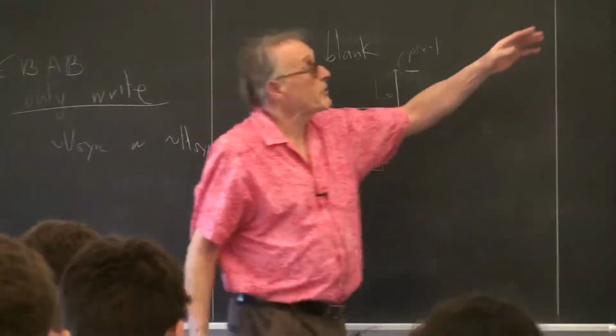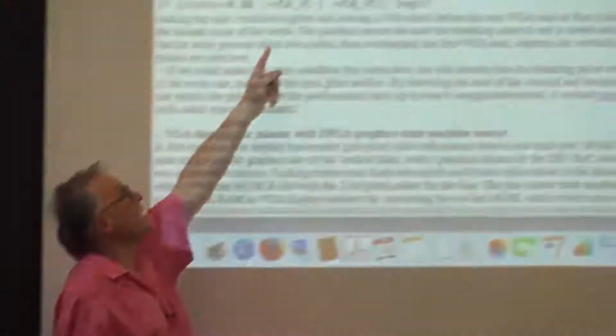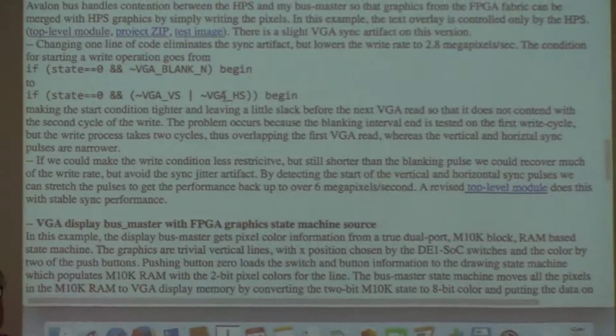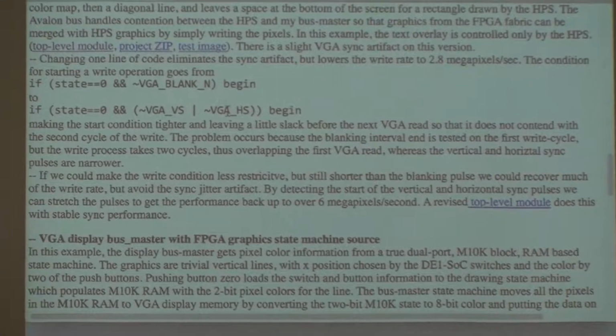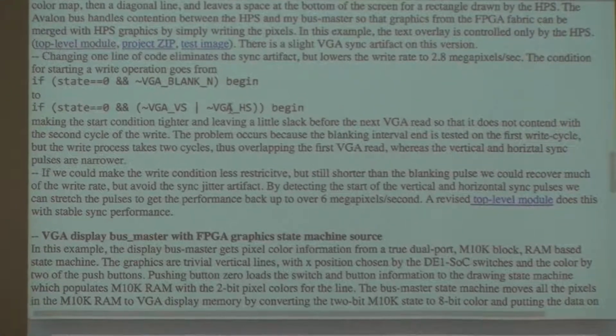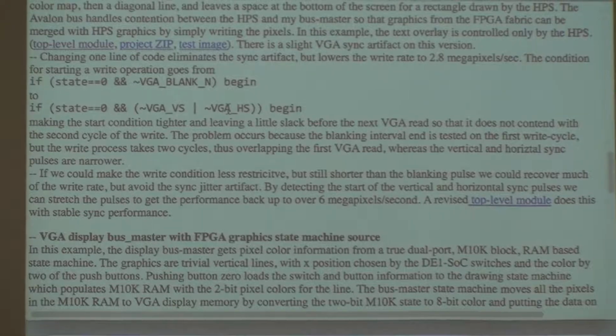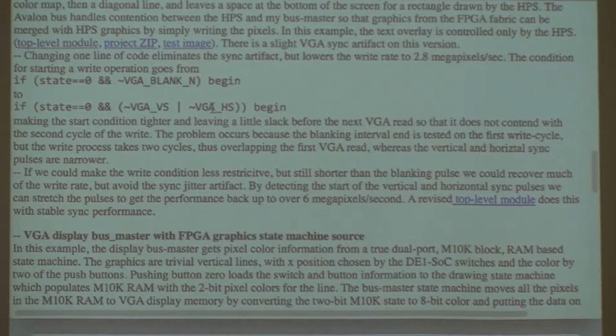In fact, you can only write when the VGA is in sync mode. Since you can't write all the time, you will miss solution states. And so you'll get a choppy looking display. The most compelling choppy looking display I saw was something that looked like this.